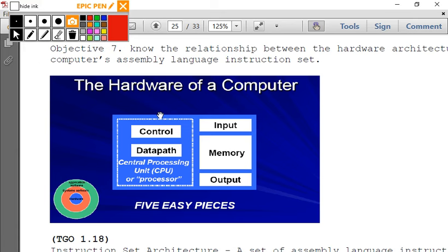Your control signal is known as an operation code, or an opcode for short. The 6 bits of those 32 go to your controller. The rest of the values go to the data path to be operated on. We're going to go into a lot more detail in this course. It performs the operation on these local copies of registers, which are very fast, dual read, single write SRAM. And then, once you're done, you want to put it back to the output.